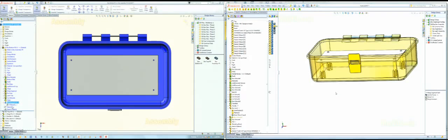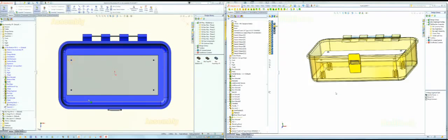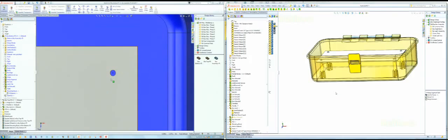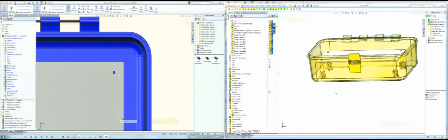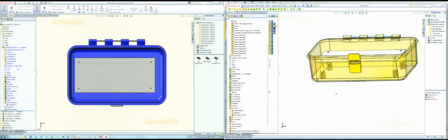It also has a 3D sketch in it, which we're going to have to deal with later when we start breaking features. Okay. Now, that gave me the first mounting boss. I had to get mounting bosses under these other holes. The way I did that was just to create a sketch on the bottom of the box, used each of these holes as reference, and just put points there. So I got these three other points, and then I just created a sketch-driven pattern to move the bosses to those positions. Okay. So that was relatively simple.